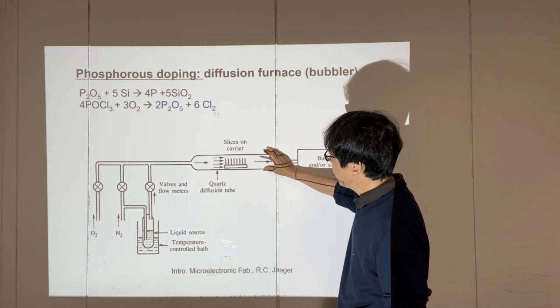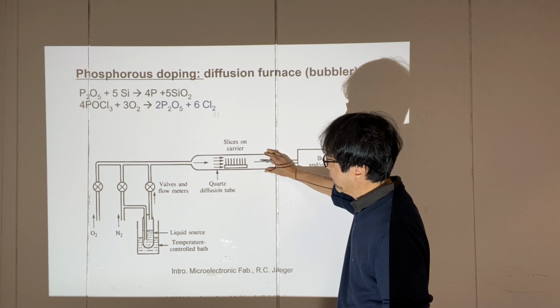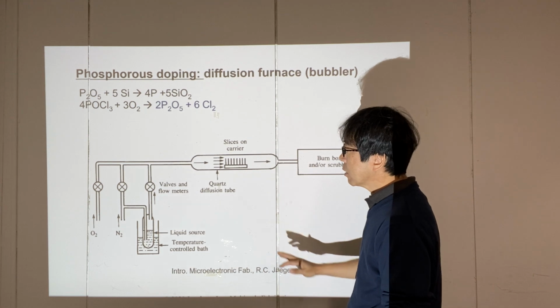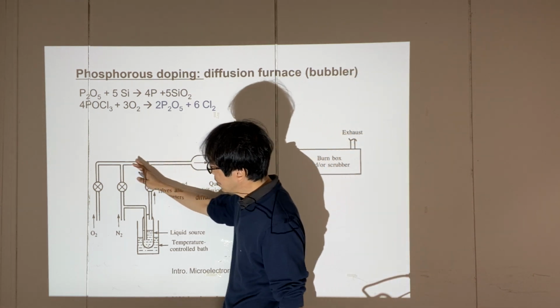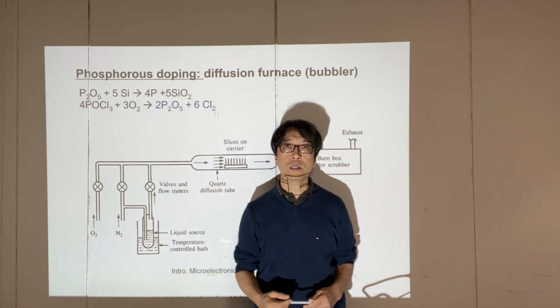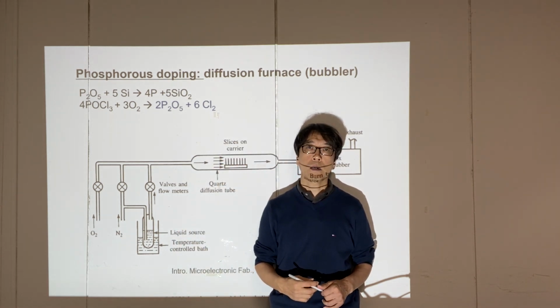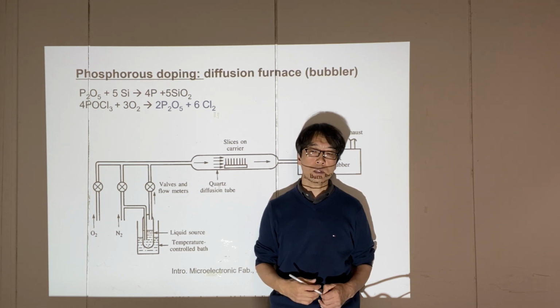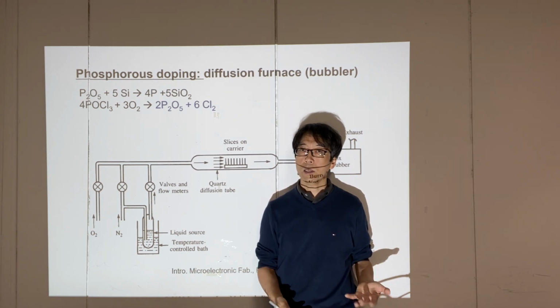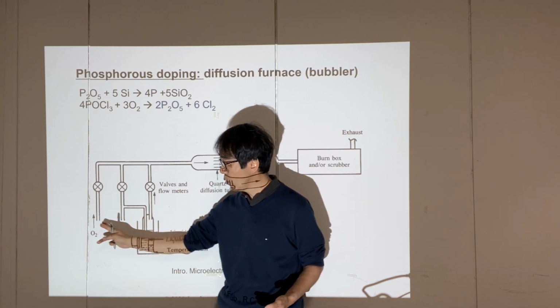So this is the furnace we saw last time. It is the quartz furnace. We have a boat where you locate your wafers, and here are lines of gas supply. Normally, people let nitrogen gas flow, which is a non-reacting gas, so there's no reaction when nitrogen is provided. Only the temperature is controlled, and then you switch to oxygen.